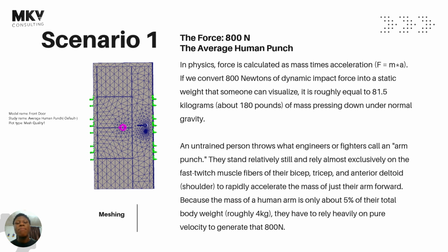Then we apply force. Because the human fist is circular in nature, we mimic a circular contact, a situation where you ball up your fist, and an average human fist is about 80 millimeters round. We put an 80 millimeter circle there. To get a circle is easy: using your split line, draw a circle, select the face and project it there, and you get your circular region. So you can select it when you're applying force. Then we apply our force, and it's done.